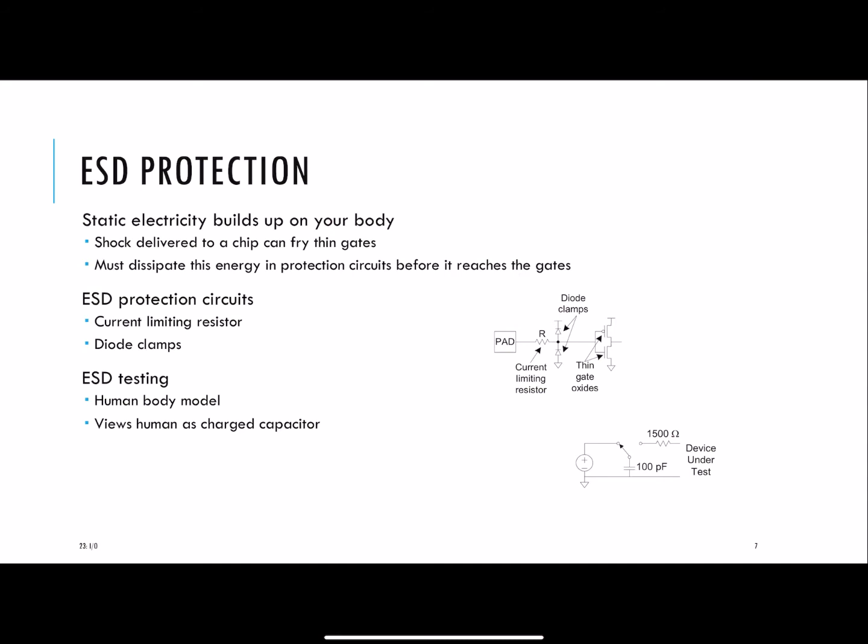So the electrostatic discharge is something that builds up. There's the human body. So let's say people touching a chip, walking around on the carpet. They don't have ESD protection on them, or smocks. There's different ways of getting rid of electrostatic potential. But let's say you don't have it and you zap the device by touching it. Then there's machines that do automatic pick and place of these devices for high volume printed circuit board manufacturing. They can pick up electrostatic discharge.